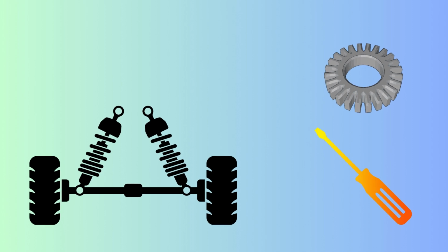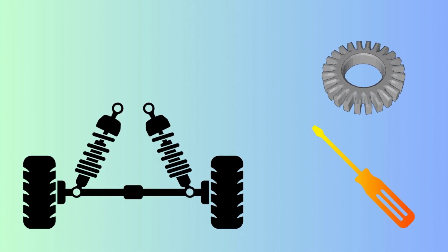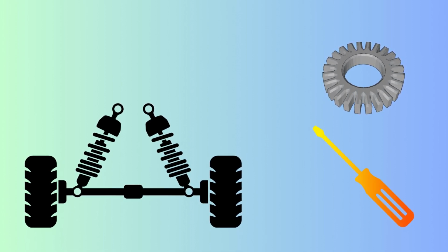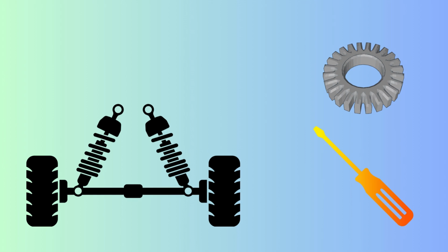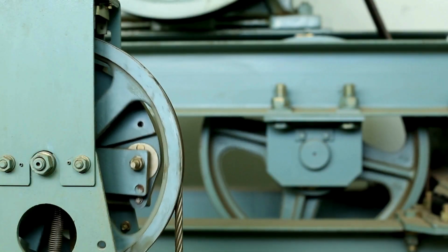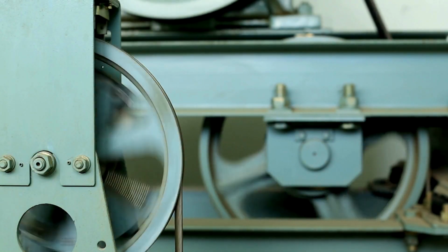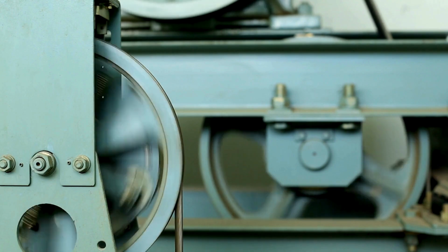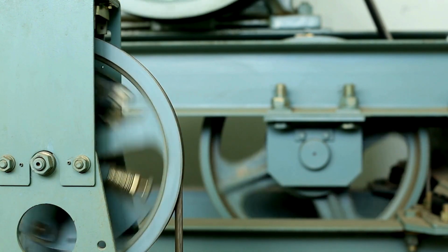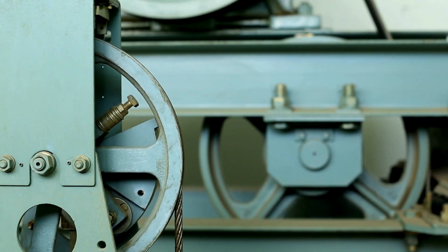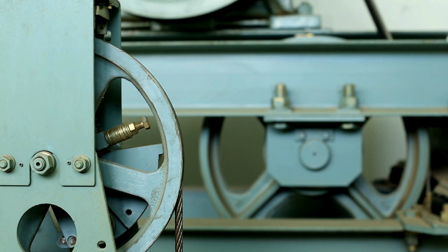Torsion plays an important role in the car suspension system. In a car suspension system, torsion refers to the twisting action of a torsion bar or torsion beam, which functions as a spring to absorb road shocks and provide a controlled ride height. Torsion bars and beams are commonly used in the suspension of vehicles, particularly in the rear suspension.